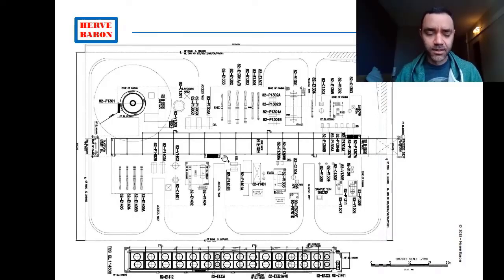But not only that, you need to evaluate the elevation of the pipelines, because when we are talking about liquid fluids, the higher the pump needs to pump it, the more head is needed. So it depends on the project.